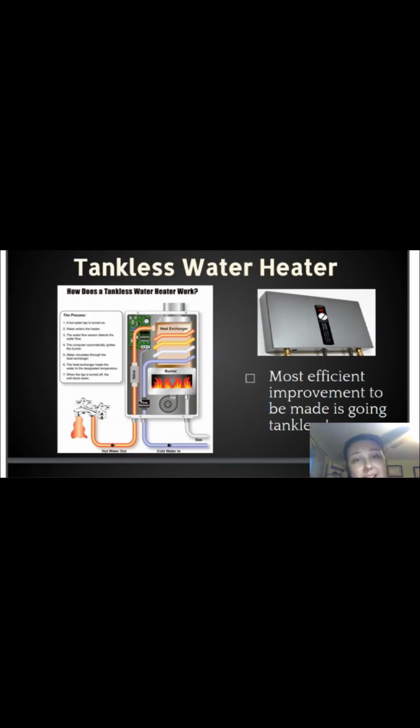If you went and found that hot water tank that I told you to go look at, and there was no tank at all, there was this funky box, you have what's called a tankless hot water heater. These are incredibly efficient, but also incredibly expensive systems that flash heat, or rapidly heat, the hot water at the moment that you're going to use it. A lot of these systems require that you turn them on ahead of time, and so you have to flick them on and give them like half an hour to heat up to get working, but they heat up the water kind of instantly or as needed for you to utilize with hot water. And those are your flash system tankless hot water heaters.